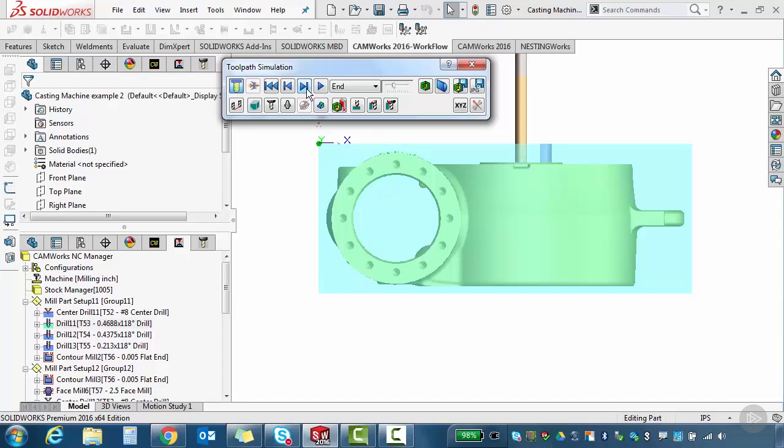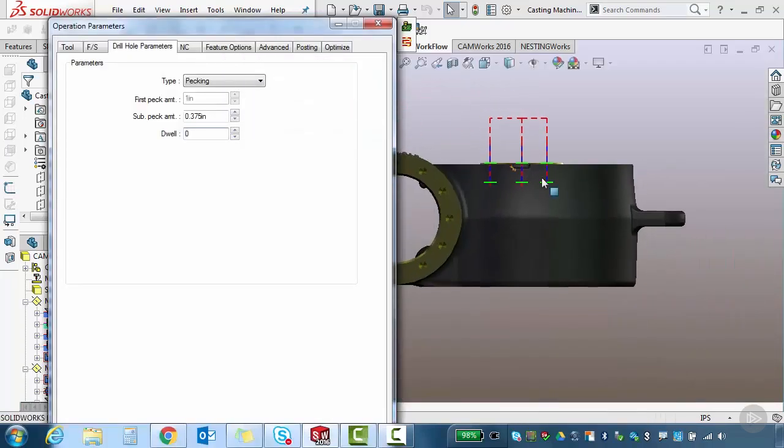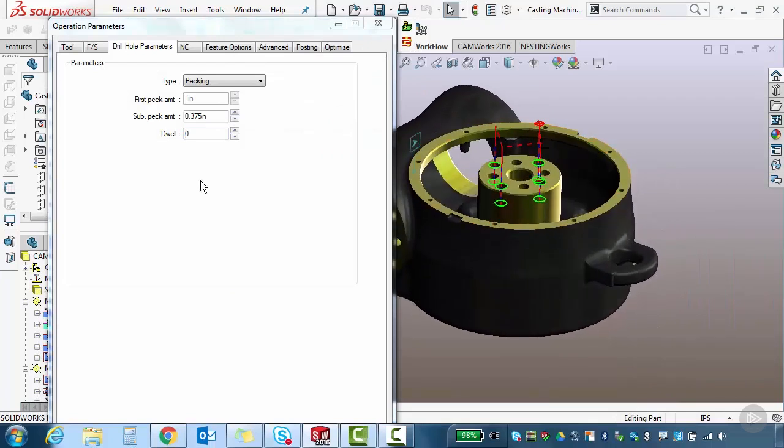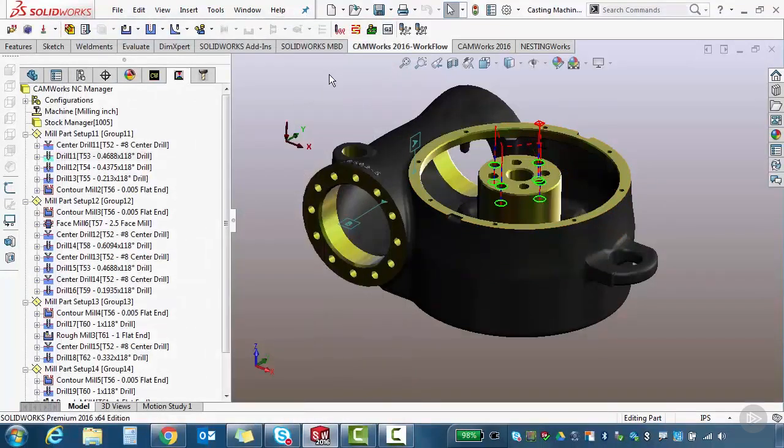And that's all based off the parameters we looked at in the original center drill and followed through the drill tool. So it's really easy to check and determine how all this information comes out. And if everything's the way we like it, we just hit X, and then it automatically brings back up the tools that we were looking at previously. For your example, we'll go ahead down here to the bottom and we'll hit OK. Again, with my display being a little bit smaller, I'm just going to hit the X. But you can go ahead and hit OK, and then those tools and features are updated.